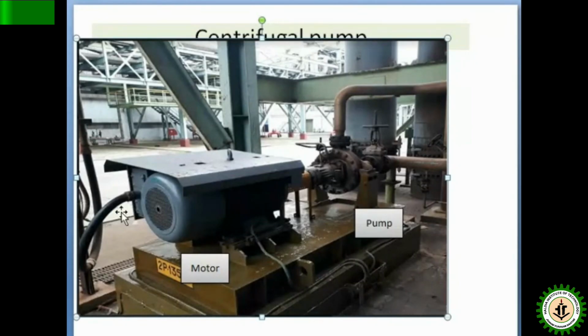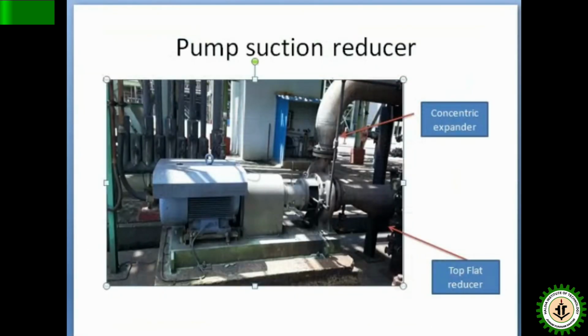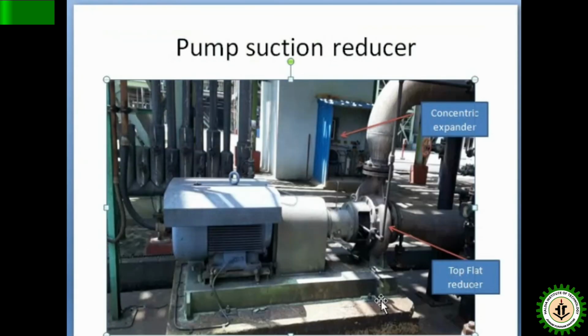And this big cable, if you see on the left-hand side, is called the power cable that gives supply to the pump. The small cables are all earthing cables and so on. So this is the side view. The side view also looks like this. This part is called the coupling. Why is this coupling used? Because it helps to isolate the pump from the motor. If there is a motor problem, you can isolate it from the coupling. No need to take out the pump, and if there is a pump problem, you can isolate it from the coupling. So that is the purpose.